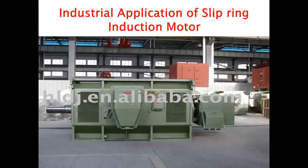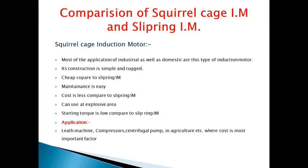So now we are going to see the industrial applications of the slip ring induction motor and the comparison of the squirrel cage and the slip ring induction motor. And we will see their applications also. If you see the construction of the squirrel cage induction motor, there is no need of additional brushes and no need of additional slip rings. So we can say most industrial as well as domestic applications use the squirrel cage induction motor because its construction is simple.